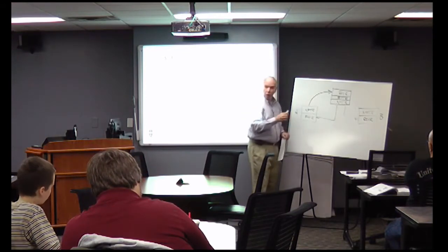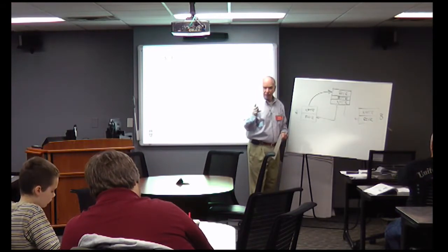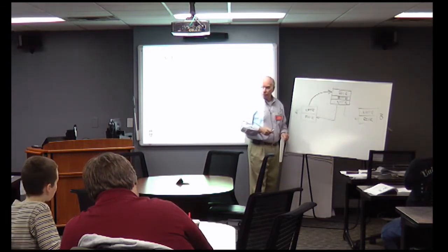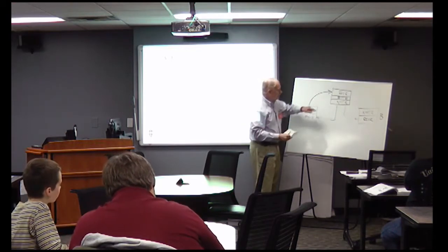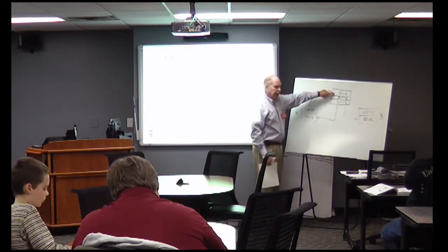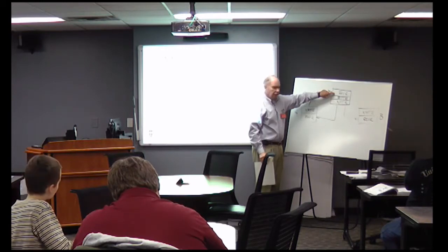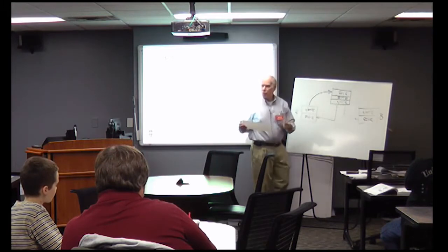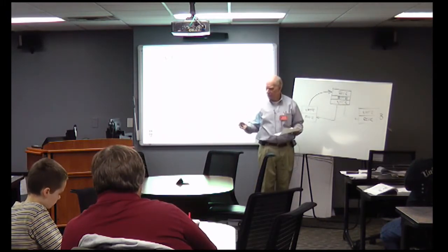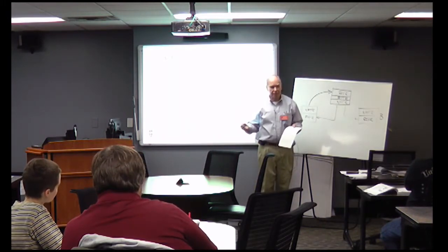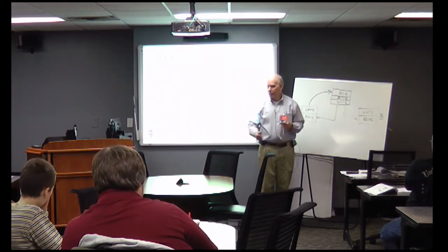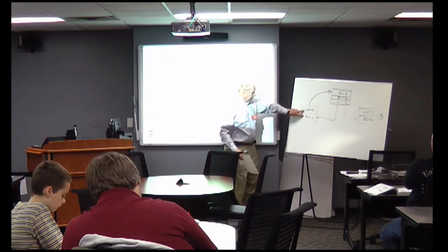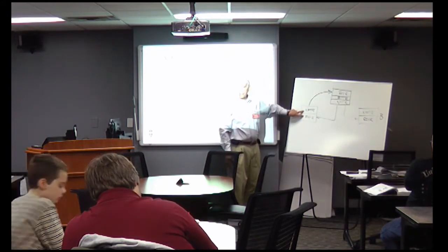The key here is that there are 2 basic frequencies involved in repeater operation, be it at the radio level or at the repeater level. One is the repeater input frequency, and one is the repeater output frequency. And the difference between those 2 frequencies is called the split, or offset. Whatever the offset is here, I've got to have the same pair of frequencies or offset established in the radio.